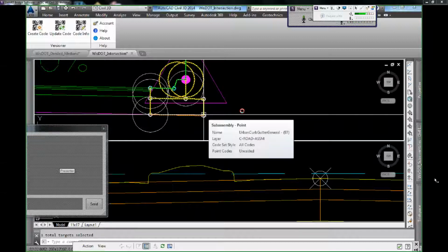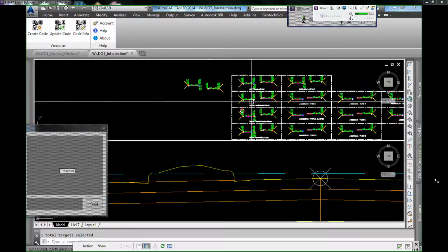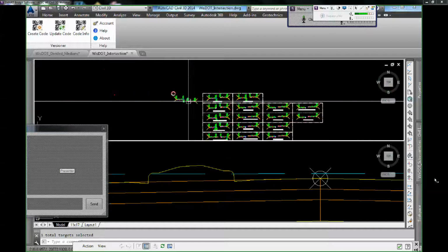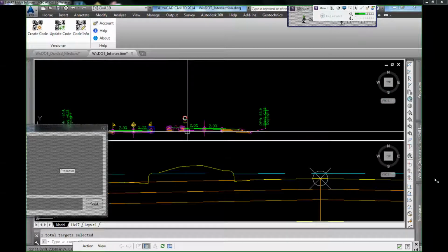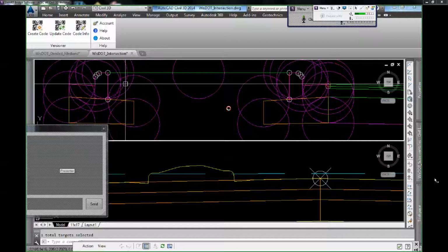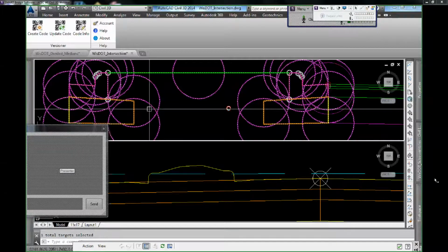Yeah, you know, our sub-assemblies create the behind the curb area a little bit different than the stock ones do. Our sub-assemblies build a terrace across the top, and it includes the top of curb. It starts at the top of curb, but it extends through past our subgrade cutout all the way out to a terrace point. Yeah, here's the stock one right here.